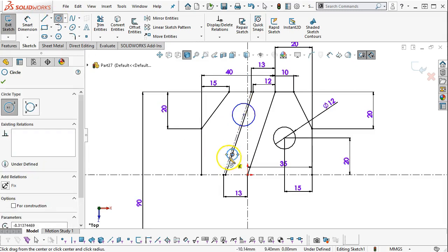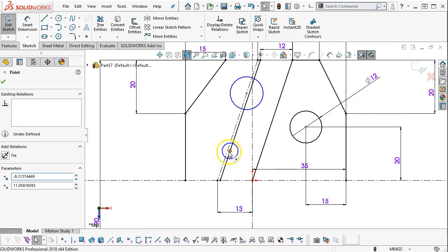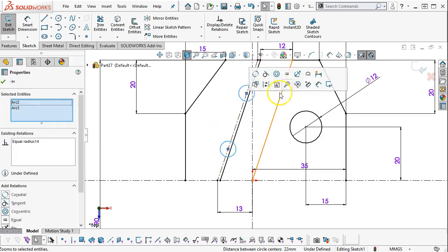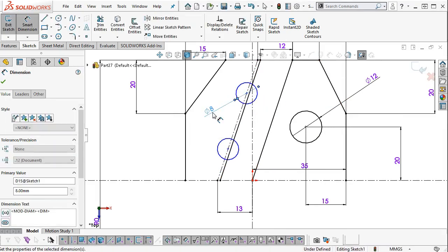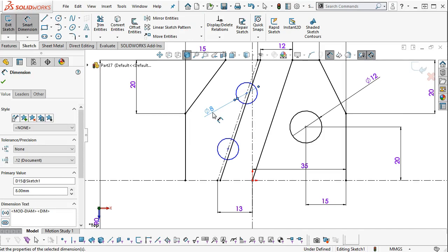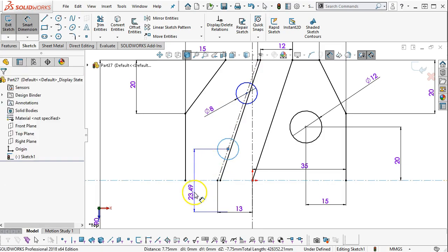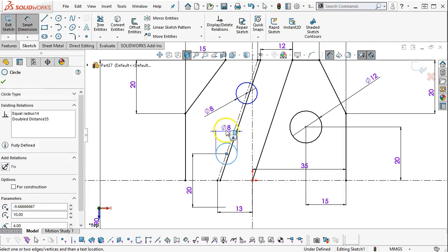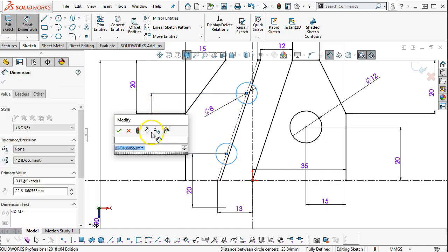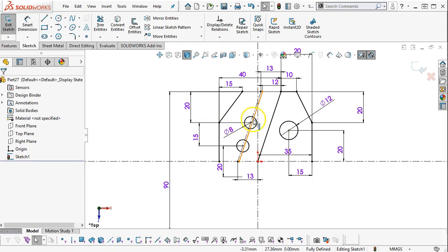All right, so that web, oh, that one jumped. All right, so let's take the coincident off, and we'll reapply it there. Set the two to equal. Apply a dimension. And those are 8 millimeters, 4 places. Has a distance of 20. And across the holes, and then between the holes is 15. So based on that, nope, it's still gonna be notched out in that geometry.